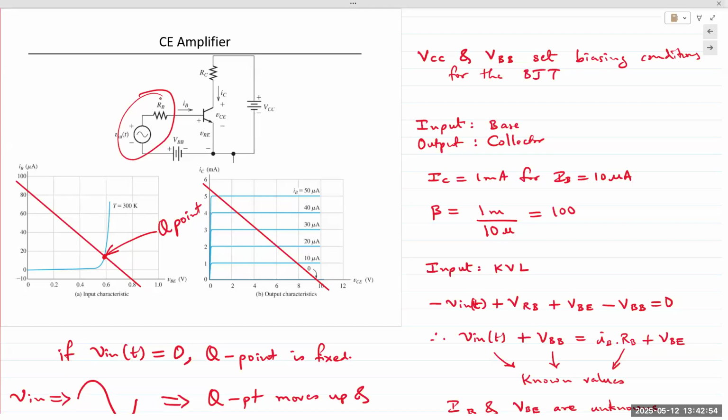So if you had two transistors, again in your lab kit you have two transistors, one of them may have a beta of 35, another may have a beta of like 100 or even 150. If the circuit works for a beta of 35 and you plug in a different transistor, the exact same make and model from the exact same manufacturer, it would have a different beta, and the circuit would result in a clipped output waveform. So this is the first circuit in base biasing.